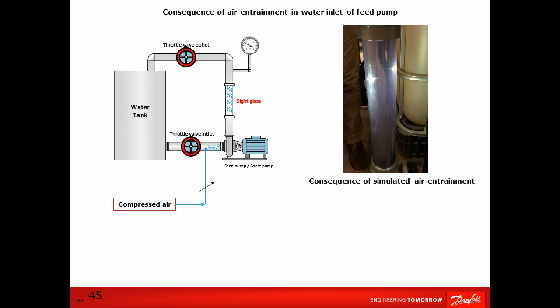First, check for visible leakages when the pump is turned on. Then, turn the system on and check shaft seals by spraying soap water onto the seals and connections that could potentially cause the problems.